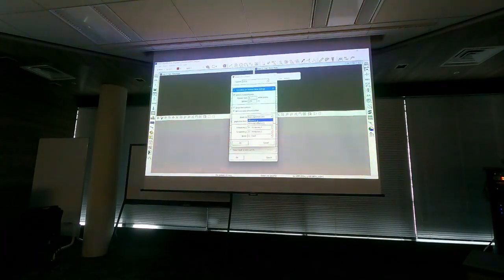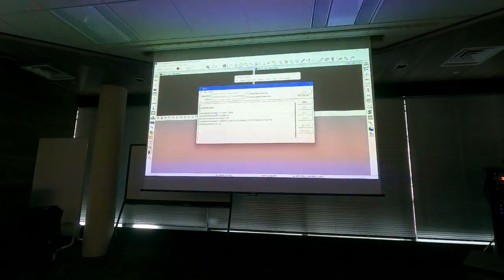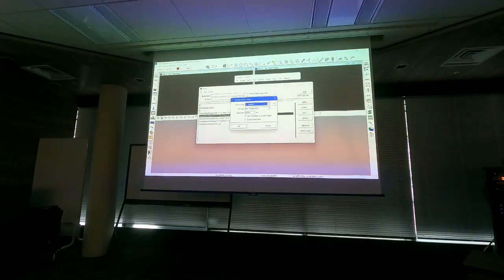But if I want to get the smoothen and remove noise steps without considering vegetation and leaving the green area points unmodified, I would go in here and make that choice and click OK and click OK, and then I get those steps that the wizard does. I get it as a macro. If my point-to-point noise is different, I would perhaps change the tolerance setting in here.